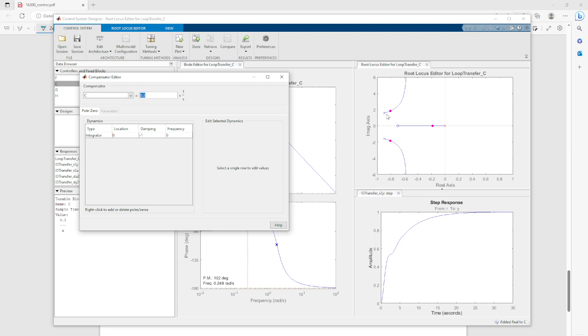And what you see is that we screwed up our system because now we have this additional pole here. It's still stable, however, we are not able to increase the damping here because the locus curves now go to the right. Interestingly, at this point, with this very low gain, we don't have any overshoot yet.